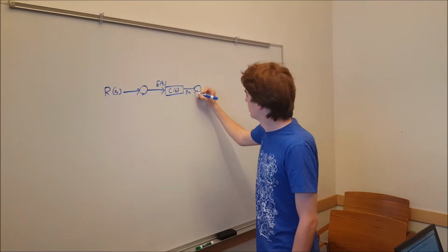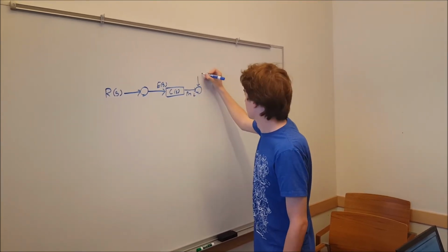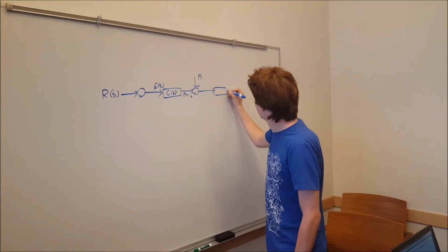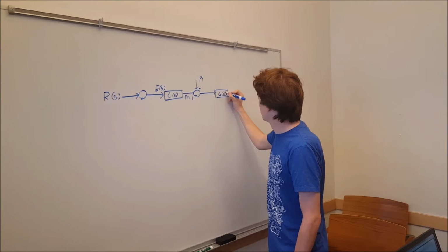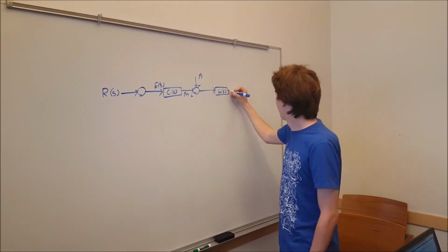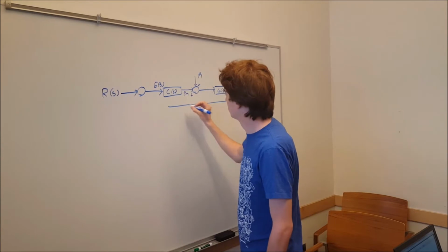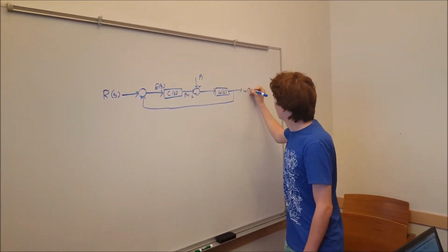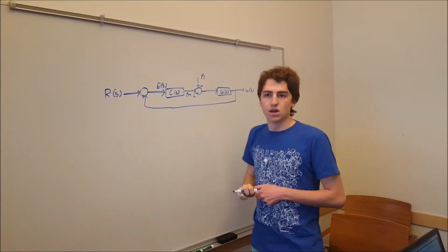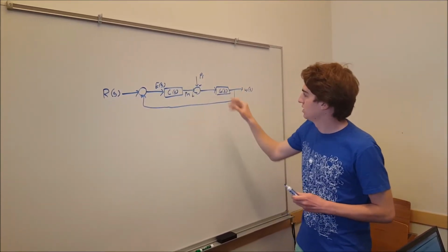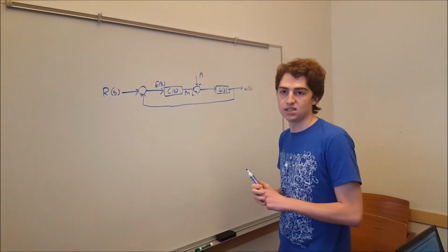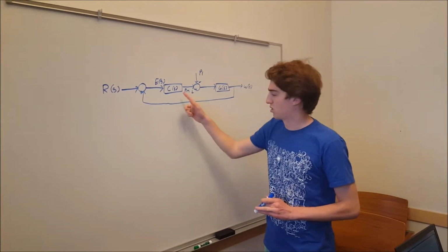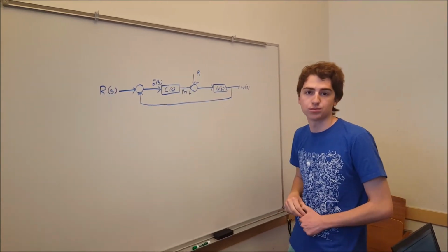That's further summed with the PL, the disturbance, and goes to G of S, which is our generator. And finally, once that is looped, that will come out as omega of S, which is our system frequency. Based on any of the disturbances, we will choose the KD and KP, which are values for settling time and percent disturbance, for our feedback controller, which is a PD controller.